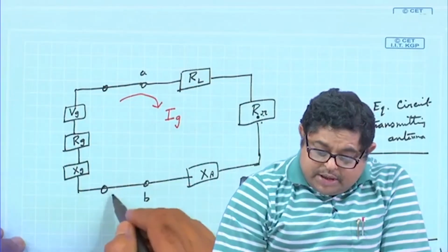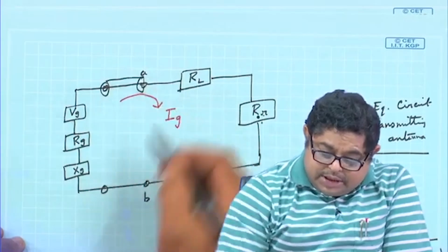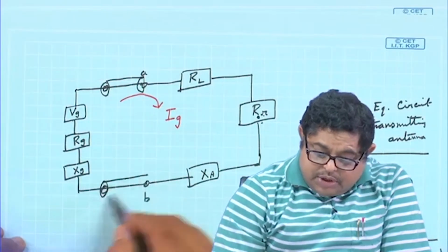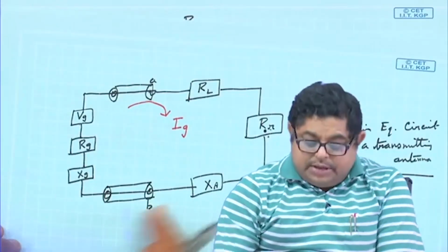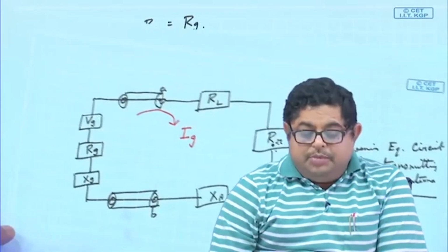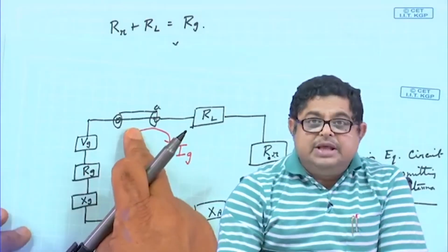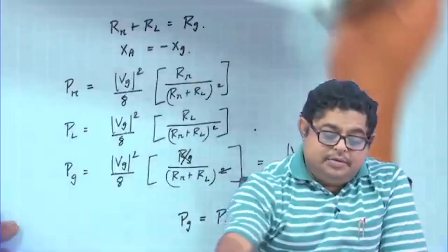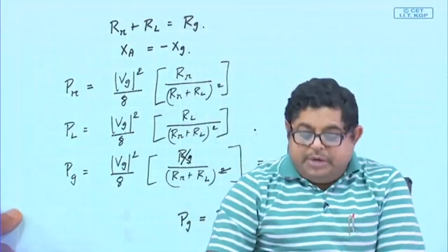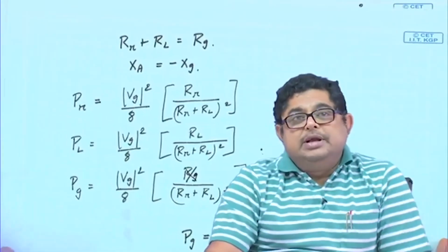So, there will be a transmission line. We are assuming that we have an impedance match on that transmission line. If not, then some amount of more power will be lost. If matched, then whatever power is supplied by Vs, half of that can be delivered to the antenna. So, you see the usefulness of the antenna's impedance.